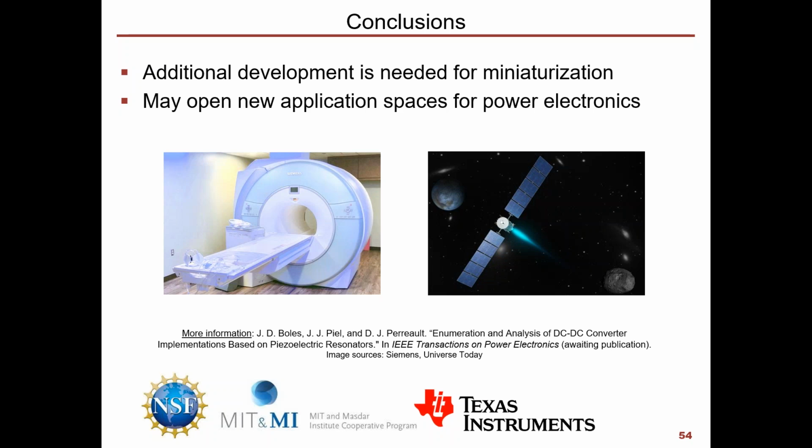So I think the main difference is with the LC resonator, you're still storing energy in the capacitance and the inductance of that resonator. Whereas with the piezoelectric resonator, you're actually storing energy in the mechanical properties, the inertia and compliance. In terms of power density, I think both could be competitive. It'll be interesting going forward to see what happens with LC resonators as well. In fact, there is some work being done on that, not by us, but by some other people. But yeah, that's a great question.